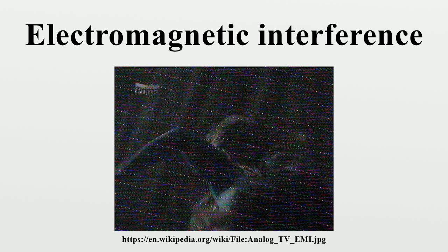Since the noise is common mode, shielding has very little effect, even with differential pairs. The RF energy is capacitively coupled from the signal pair to the shield, and the shield itself does the radiating. One cure for this is to use a braid breaker or choke to reduce the common mode signal.